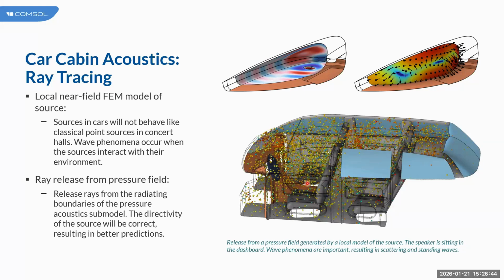And this model also shows you how you can switch from a full finite element model to a ray model as we move towards very high frequency, as we also saw in the earlier example on modeling an ultrasonic car parking sensor, where the sensor was modeled using the finite element approach in detail, and the integration of the transducer over a large platform and analysis of the sound over large distances was carried out using the ray tracing approach.